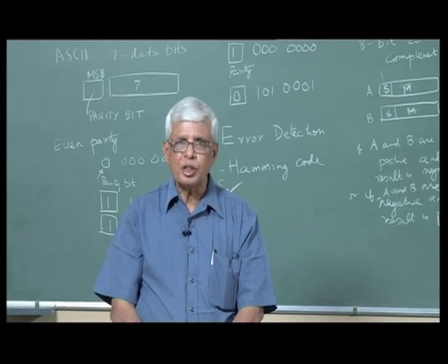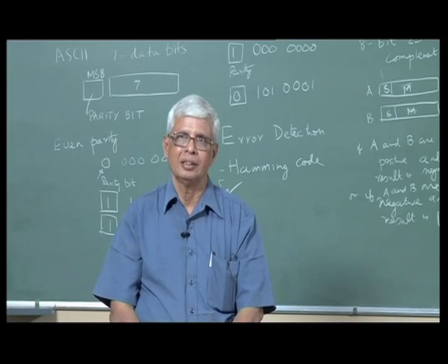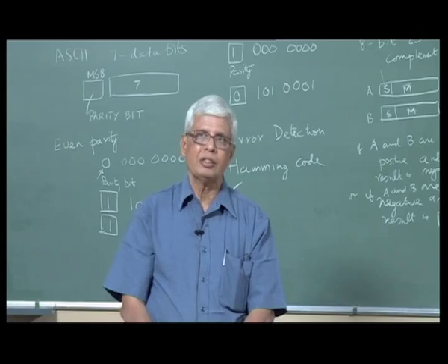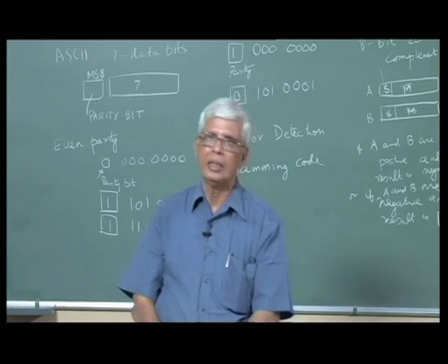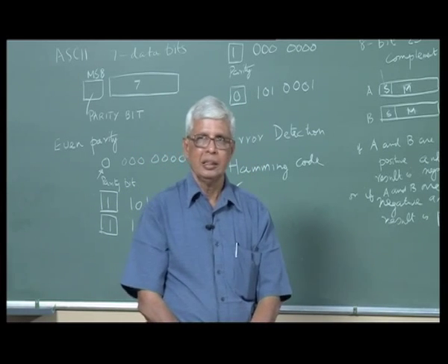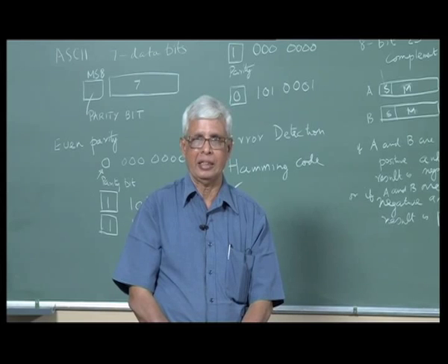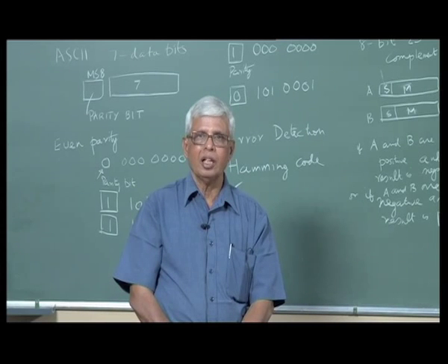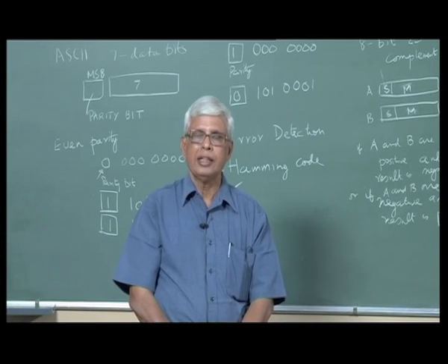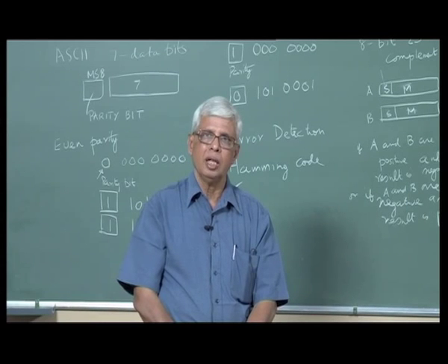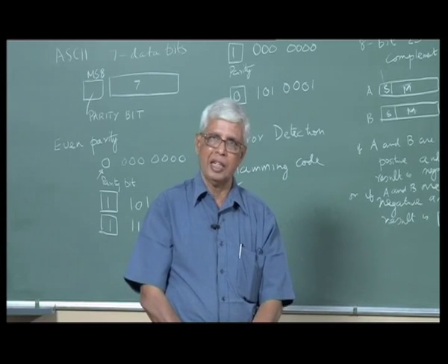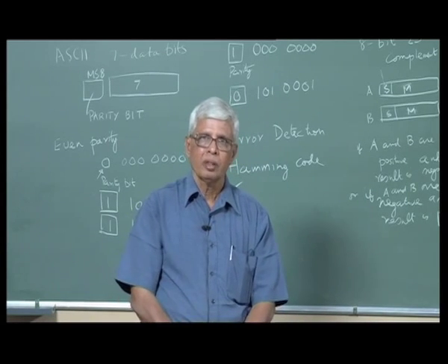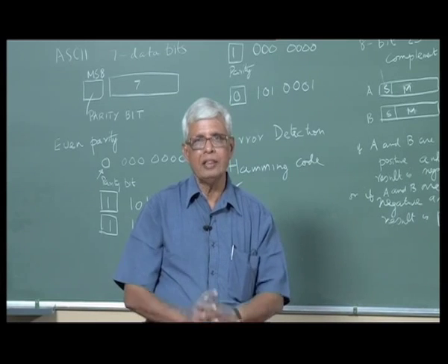If you try to push a number greater than this into the register that takes the result, then the number will not be right. That is called an overflow error. You can detect this overflow, scale your numbers A and B to make them smaller, add them to get correct results, and then you know how much you scaled.